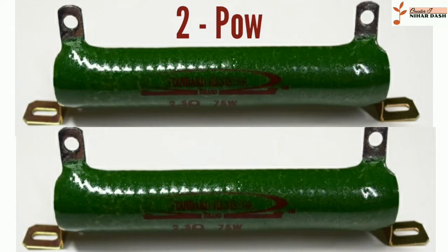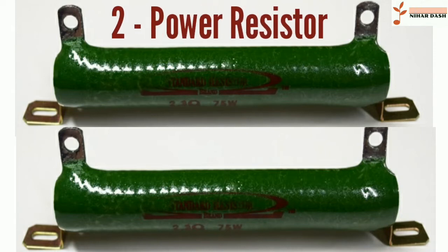Power resistors. Power resistors are designed to withstand and dissipate large amounts of power. In general, they have a power rating of at least 20 watts. They are made from materials with a high thermal conductivity, allowing efficient cooling. They are often designed to be coupled with heat sinks to be able to dissipate the high amount of power. Some might even need forced air or liquid cooling while under maximum load.